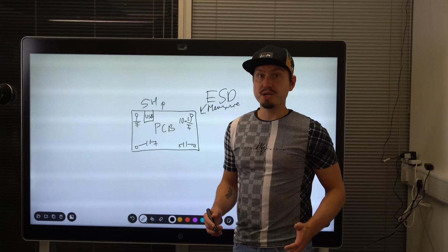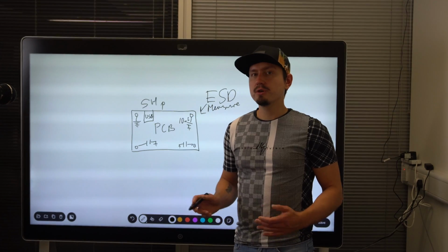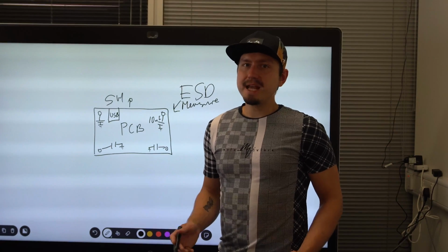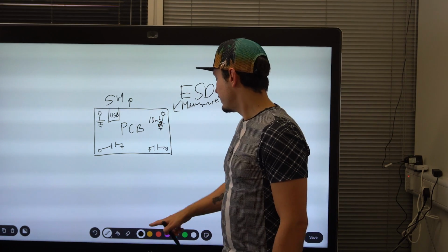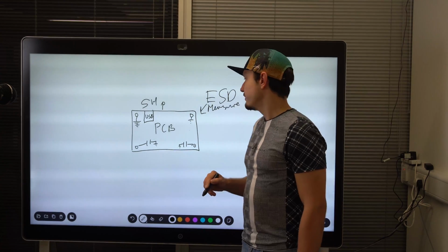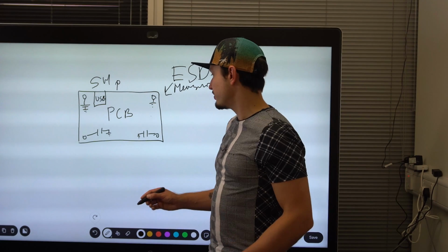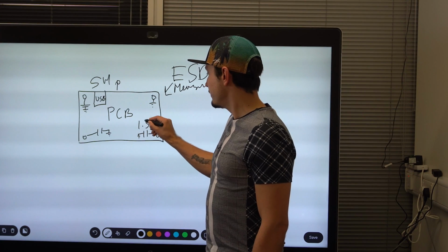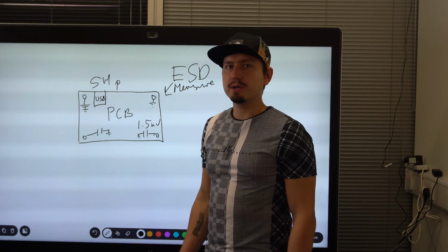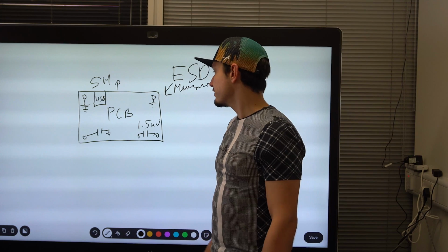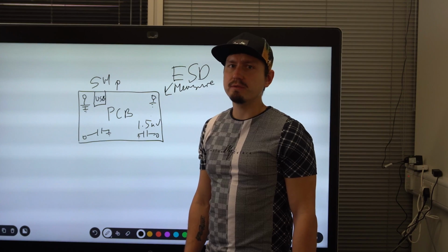If you do not have USB, you may want to make this connection at another high frequency signal such as coaxial. And if you do not have any of this, then you simply use one of those connections and connect it directly to ground with either a 0-ohm link or something similar. And one thing I didn't mention is that the capacitors must be at least 1.5 kilovolts rated, otherwise they will simply break when the ESD is applied. So this is also quite important to maintain isolation between shield and 0-volt plane.